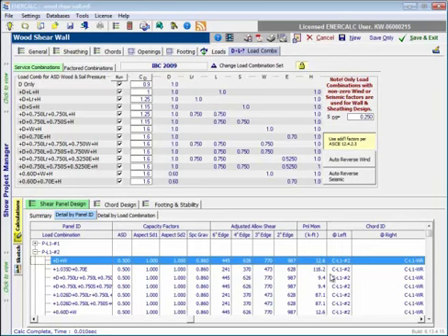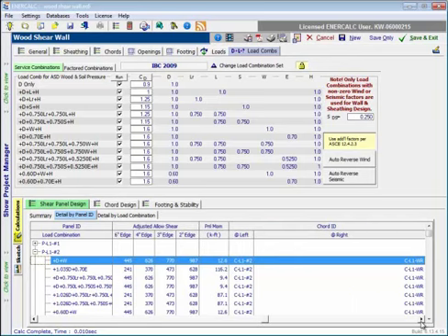Okay, then moving over, we have the panel moment indicated here in units of foot-kips, and finally, for convenience, we identify the chords at the left and the right end of each panel. So the left hand chord for the panel L1 number 2 is called chord L1 number 2, and the right hand chord for the panel L1 number 2 is referred to as chord L1 WR, which stands for wall right.